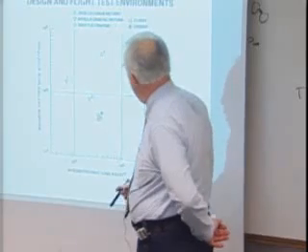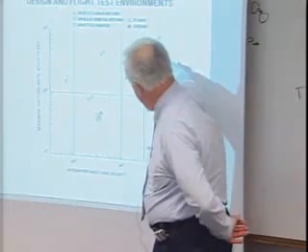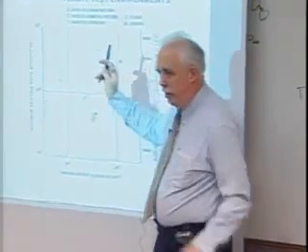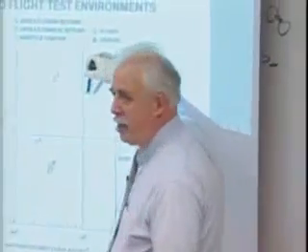Okay, so let's start with the Apollo. Our design is up here, coming back from the moon. Actually, there were two design points. This was the maximum load, which was the thickness of the ablator. That's the weight. Okay, we picked the material, we got the best material we could. Now the question is, how thick do we make it? And that's the weight. Here's the design condition.